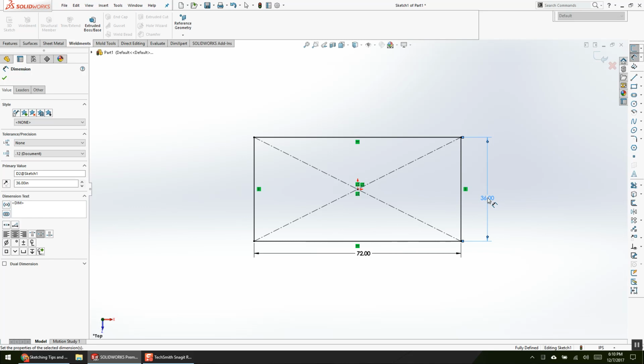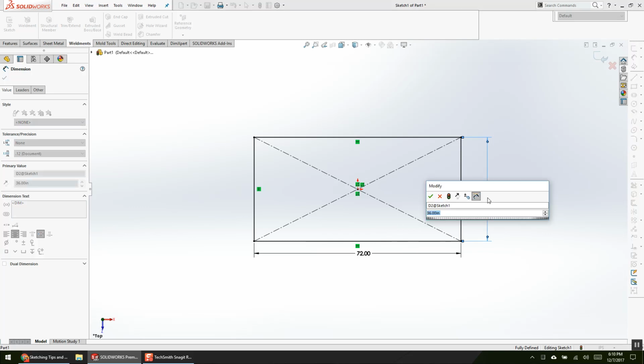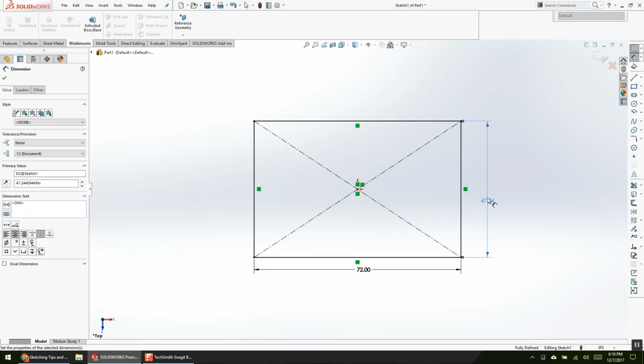So if I have to design these hybrid metric environments, which, who all hates metric? Yay! Okay. So if I have to design hybrid metric environments, and they tell me it's 1200 millimeters, I'm going to do 1200 mm, enter. So tip number 1. There's a mixture of speed tips, and then there's a mixture of stability tips, right? So speed tip number 1, SolidWorks has a full unit converter built into the software.